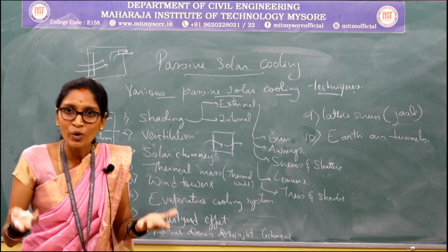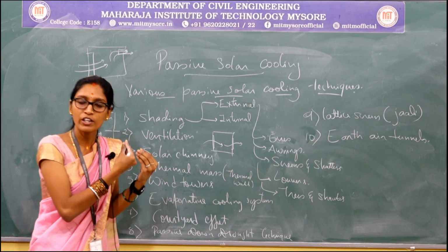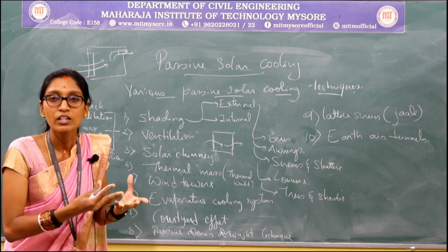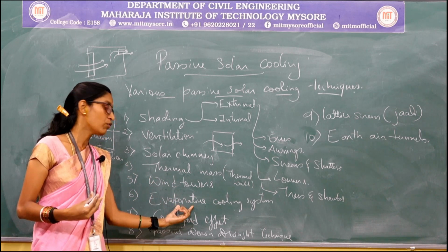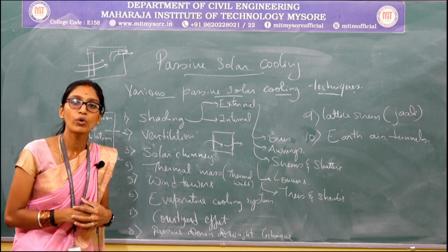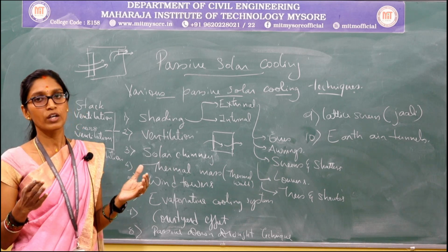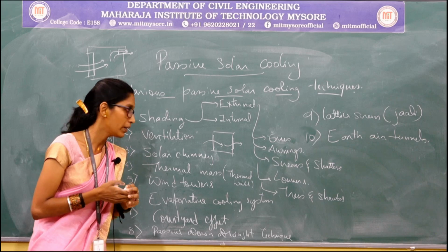Those are also provided as a particular strategy, in order to get a particular useful thing to the interior, right? So this is how evaporative cooling happens in a system in order to achieve passive cooling in a particular building.